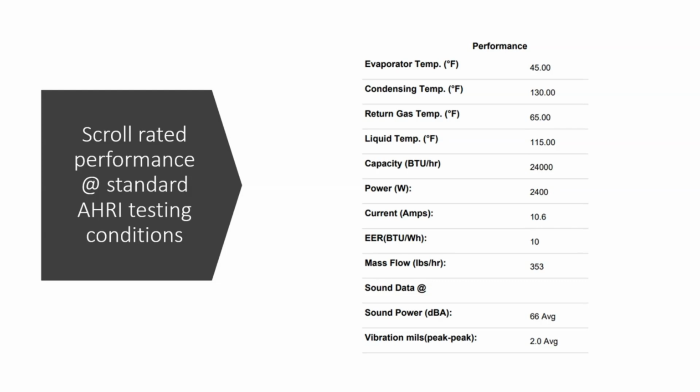In a real-world application, we know that this equipment will be subjected to many different conditions throughout the day, the week, and the year. And we also know that airflow can affect the coil performance, whether it is a filter issue, ductwork leakage, humidity levels in the space, or even ambient conditions outdoors.